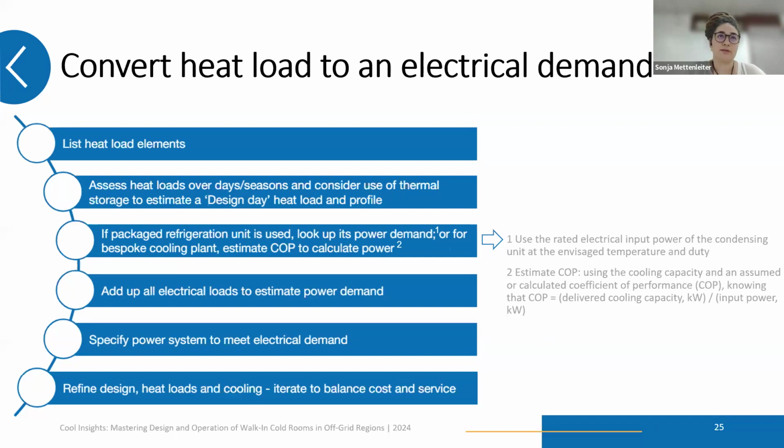Most times there is also some telemetrics included. So you list all of that, and that's how you calculate your power demand. And then from that, you specify your power system to meet that demand, and then you refine that design according to your load profiles, and also find a balance between your loads and your costs. Next slide, please.